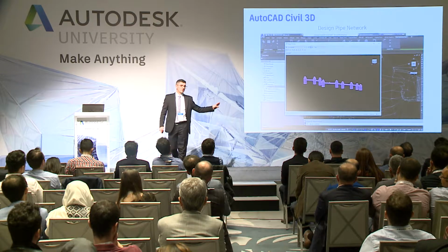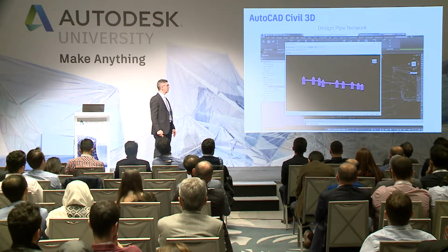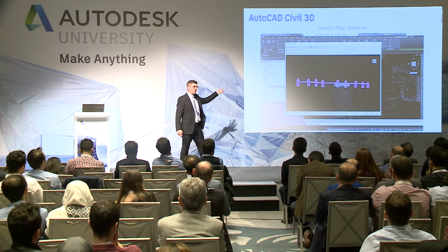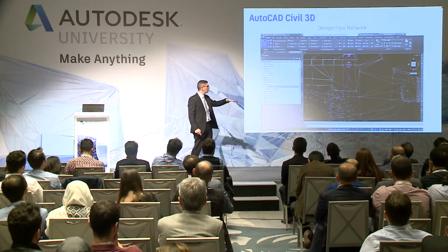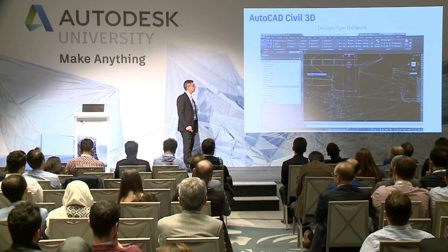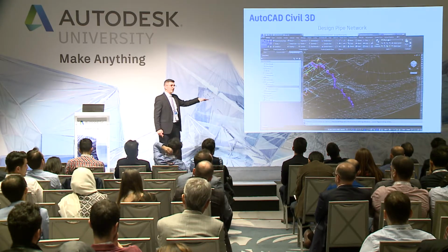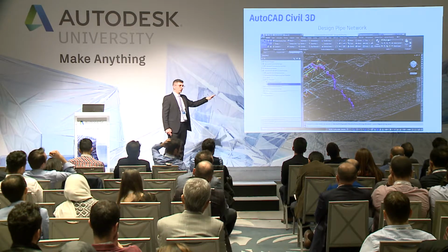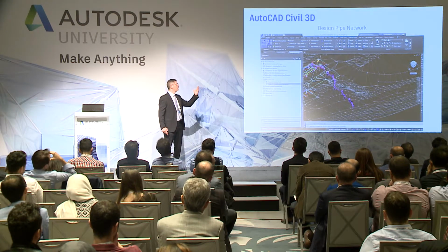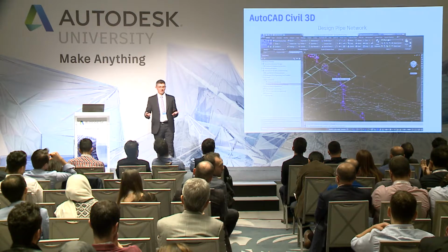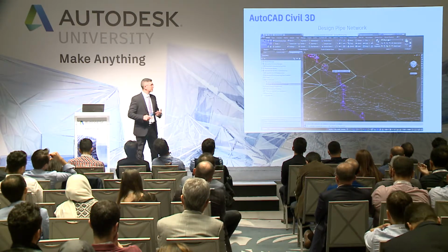I immediately have the representation of my sewage system, where we have a pipe with 1% of slope, and where we have a structure. Again, we have the possibility also to manage dynamically any change inside this type of model, because we can change slope, we can change representation, we can change diameters, and that's it.